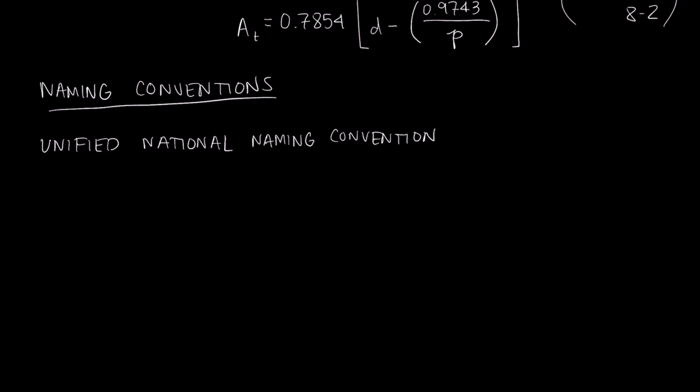Okay, and a typical bolt spec you might see may look something like this. 1/2 inch, 12, UNC, 3A, and we'll add the LH. Okay, take a second, try to guess what you think this all means, and then when you have your answer, unpause the video, and let's work through it.